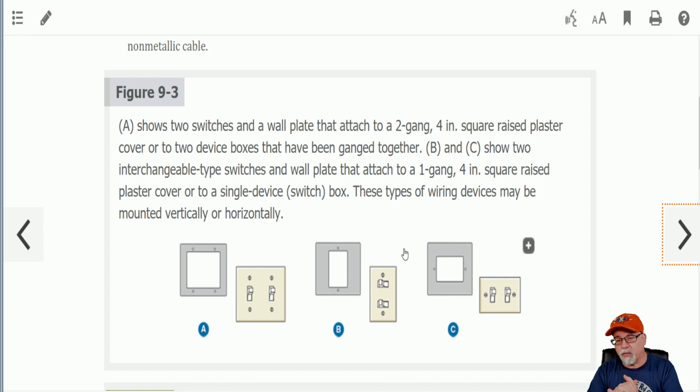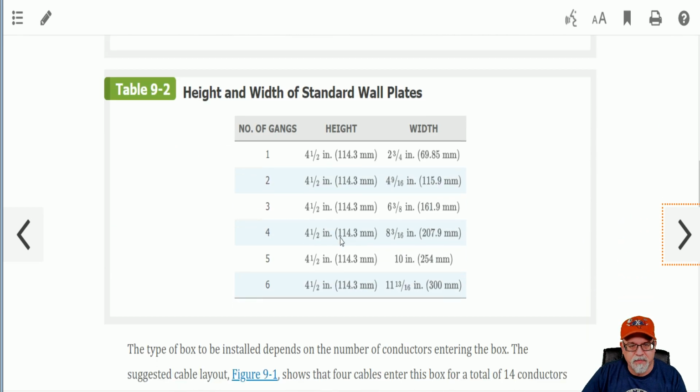Now, you've got to be careful with a couple things. When it is a switch with the on, it should be on in the up position. But a lot of switches like that, three-way switches, won't have any markings. Really doesn't matter. Just be aware of what you're doing, what you're selecting, and how you're doing it. Okay, but there you go. Now, height and standards, boxes.